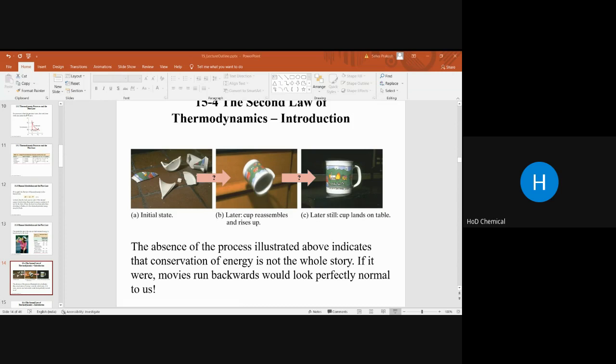As usual, it's given by the heat pump. For a heat pump, the coefficient of performance is simply QH divided by W. If it is a refrigerator, it's QL divided by W. Okay, how the work is transferred into the system and how the energy is transferred.